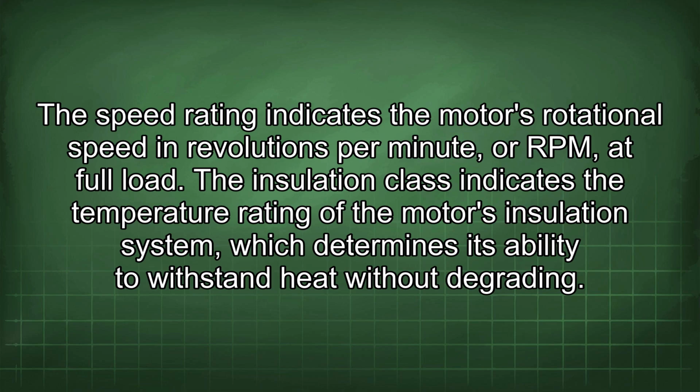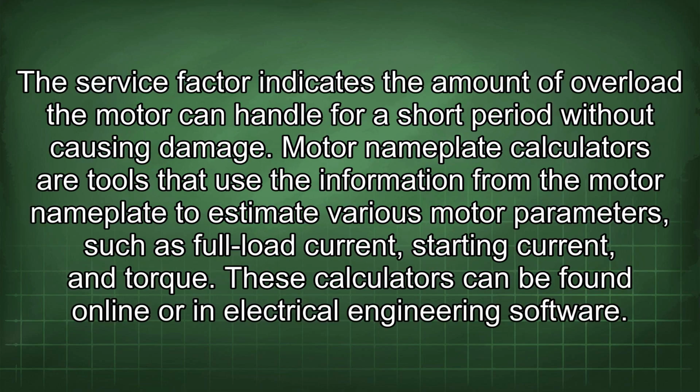The insulation class indicates the temperature rating of the motor's insulation system, which determines its ability to withstand heat without degrading. The service factor indicates the amount of overload the motor can handle for a short period without causing damage.